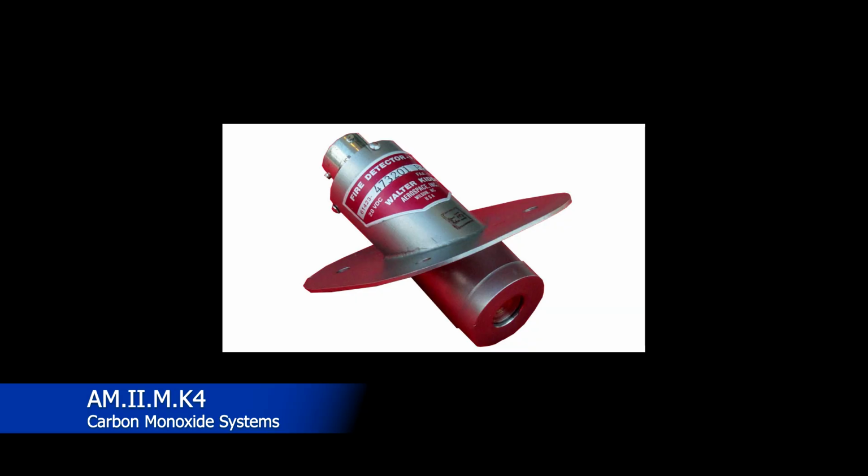Okay, so another type of detection system that you'll come across is a flame detector. This is literally an optical sensor that detects a flame itself, which is super cool that it can be done, but smoke typically comes first. You're going to detect the fire sooner with smoke than you will with fire. However, there are certain situations where flame is going to be easier to detect than smoke. Let's say you're in some sort of area where there's a lot of wind churning. You're going to see the flame probably before you actually get enough smoke there to detect it.